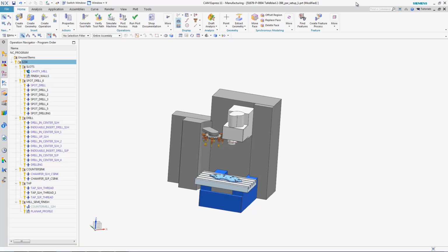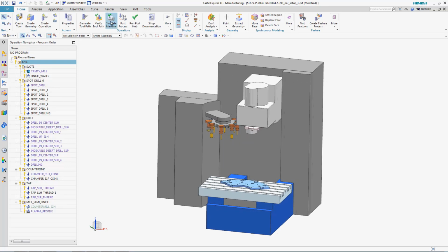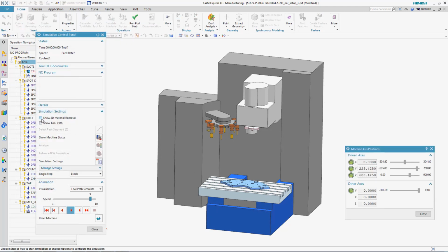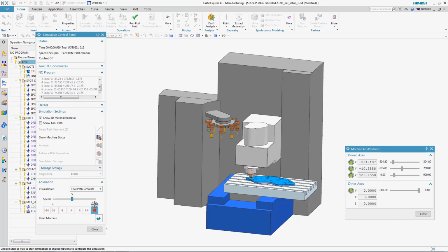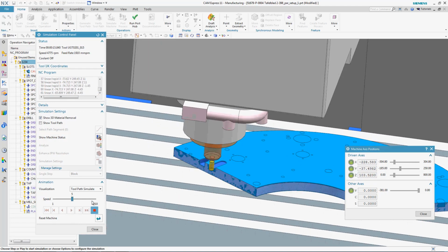Most industrial machinery components are still manufactured using more traditional machining processes, known as computer-aided manufacturing, or CAM for short. In order to manufacture this table segment, we'll utilize a milling process. Here, Solid Edge CAM operates directly on the 3D model, allowing for intuitive creation of associative toolpaths.